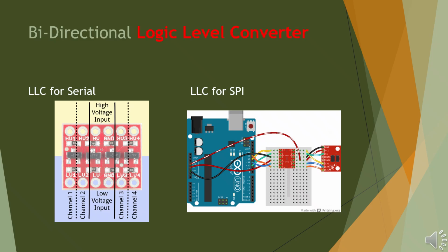There are two main types of level converters: unidirectional converters, which allow signal flow in only one direction. These are suitable for one-way communication lines like TX, transmit, or SPI MOSI. Bidirectional converters, which allow signal flow in both directions automatically. These are ideal for two-way buses, such as I2C, where the same line is used for both sending and receiving data. In some cases, resistor-based voltage dividers can be used as a simple, low-cost alternative for slow-speed unidirectional signals. However, for high-speed or bidirectional protocols like I2C or SPI, dedicated MOSFET-based level shifters are preferred because they maintain proper signal integrity and timing.